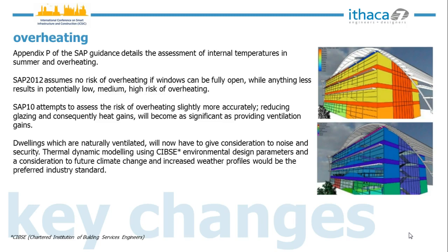And then finally we have overheating. Under SAP12 we would say that if you open the window, then you have no risk of overheating. Under SAP10, that goes out of the window. Depending on whether we have, for example, an apartment on the top floor, we might consider overheating to be a problem, so you need a more thermodynamic model to go through it.